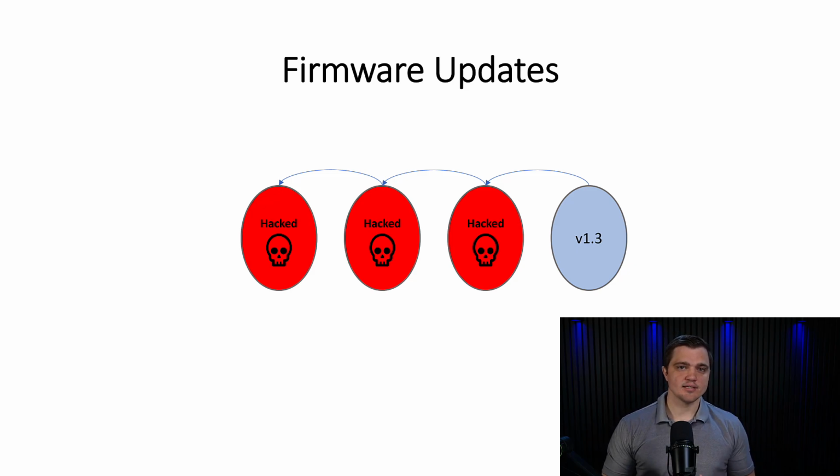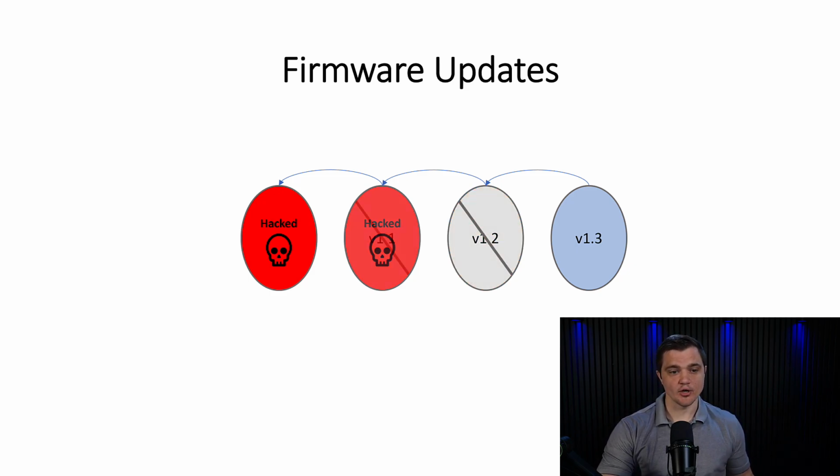The way that the CEC173x prevents against this type of attack is we can uniquely identify each of these firmware images so that during the secure boot process, not only do we have to establish a legitimate digital signature, but we have to check to see if the ID that's being presented hasn't been previously banned. So we can gather a list of the versions of the code that we no longer want to be considered legitimate anymore, and even if they have been provisioned using the correct private key, they won't be allowed to run because we have protected against the rollback of that code.